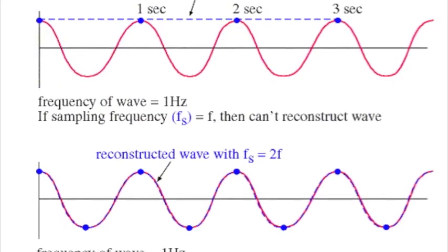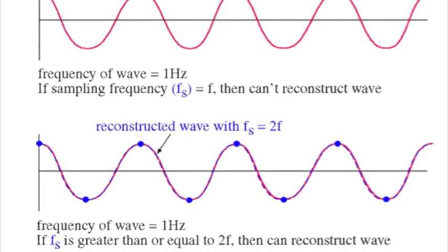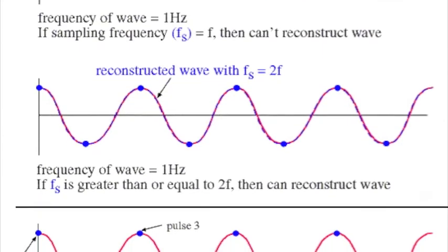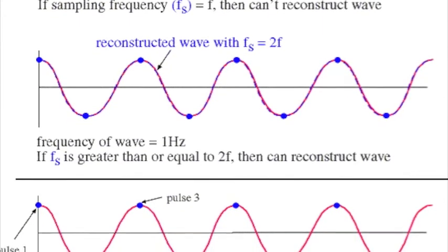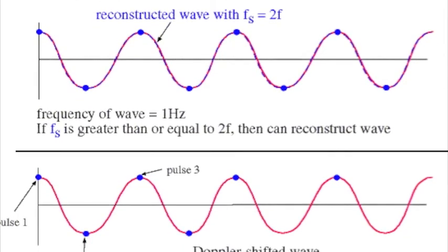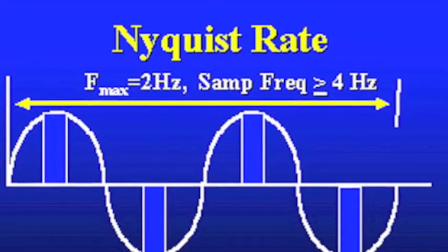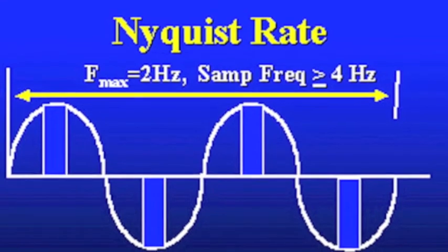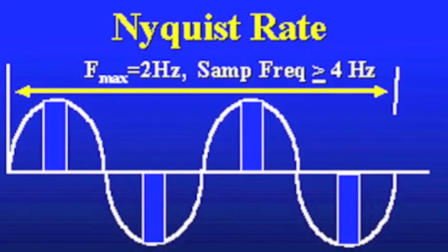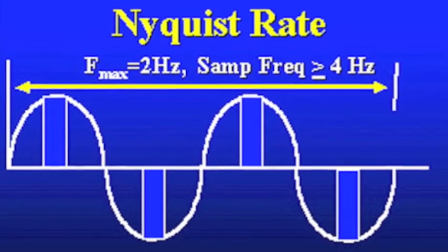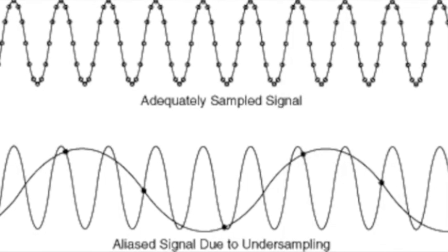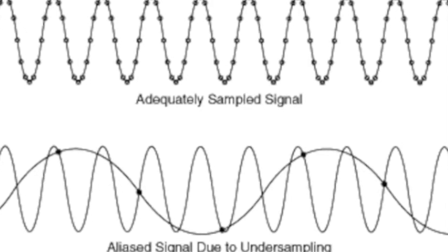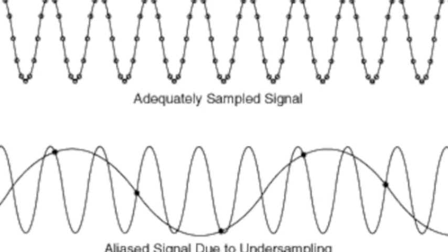Two important concepts in data acquisition are Nyquist frequency and aliasing. The Nyquist frequency is half of the sample rate and must be greater than or equal to the frequency of the highest frequency component of the system in order to ensure accurate data acquisition. As a result, the sampling rate must be at least twice the frequency of that component. Any information occurring above the Nyquist frequency might be confounded during data acquisition, and that is known as aliasing. In aliasing, signals become indistinguishable from each other and can seriously distort results. You can find more information on this in the resources section of your assignments document.